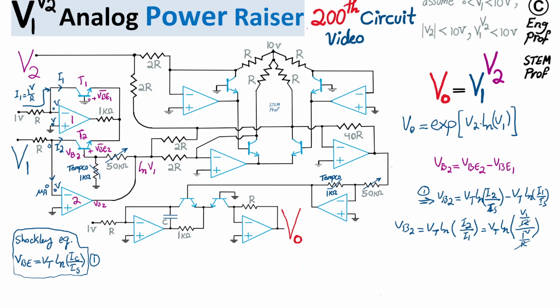Just a general recommendation: the resistors in this circuit are suggested to be low tolerance. If you can use thin film, that would be a good idea, but basically less than 1% variation, which is nothing strange. It would just help increase the accuracy of the circuit.